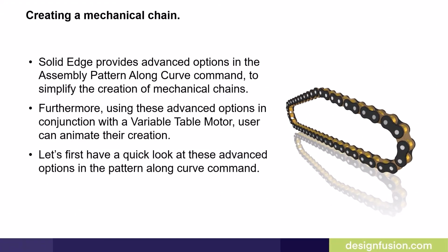Solid Edge provides advanced options in the Assembly Pattern Along Curve command to simplify the creation of mechanical chains. Furthermore, using these advanced options in conjunction with a variable table motor, users can animate their creation. Let's first have a quick look at these advanced options in the Pattern Along Curve command.